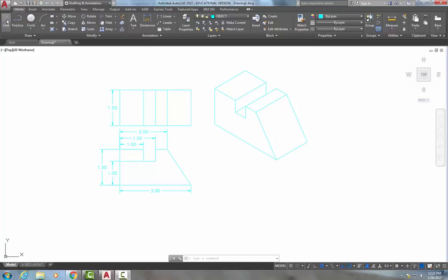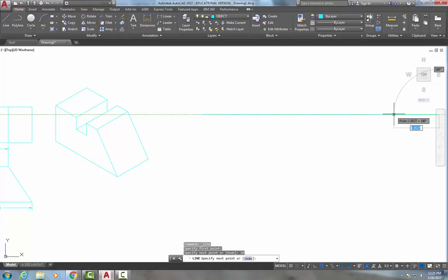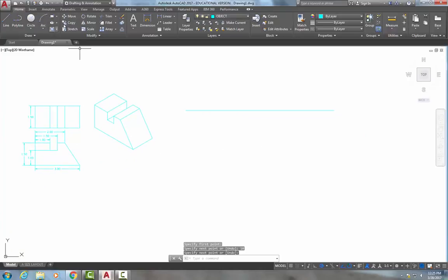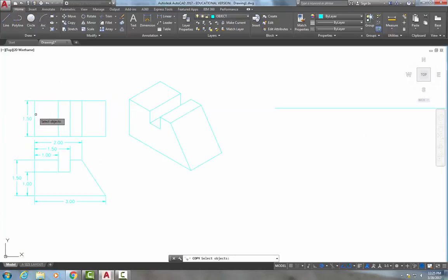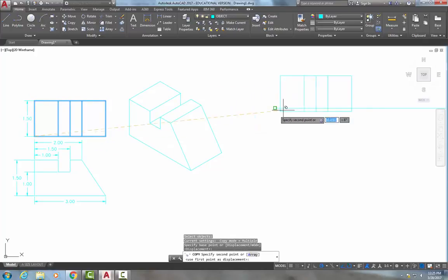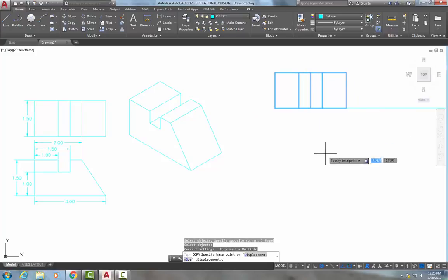If you remember from a 1 point, we have our top line that represents our picture plane line. So if I start out with my picture plane line here, I'm going to make it a random length to start with. We can always adjust it later. Remembering back to 1 points, we put our top view in on the top line there. So I'm just going to move this over here, and I'm going to move it in just a little bit so I have the tail of the line.